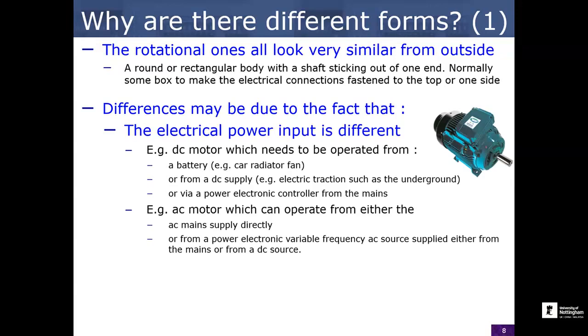We also have AC motors. So AC motors could be supplied directly from the mains, as we'll talk about later in the course. Some motors, like induction motors, are actually ideal for simple plug-and-play applications, where you can plug them directly into a mains three-phase supply, put a mechanical load on them, and if it's within their capabilities to drive it, they basically will. You don't really need any kind of control, external switching, drives, feedback, anything. They're very, very simple plug-and-play devices.